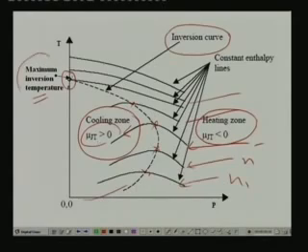And what is the significance of this maximum inversion temperature? You will see that when the initial temperature is higher than the maximum inversion temperature, that means throttling is taking place in this region, you find that it always increases the temperature. So if you want to reduce the temperature of a gas during throttling, its initial temperature must always be lower than the maximum inversion temperature. This is a necessary condition for reducing the temperature during throttling. Of course, this is not a sufficient condition.